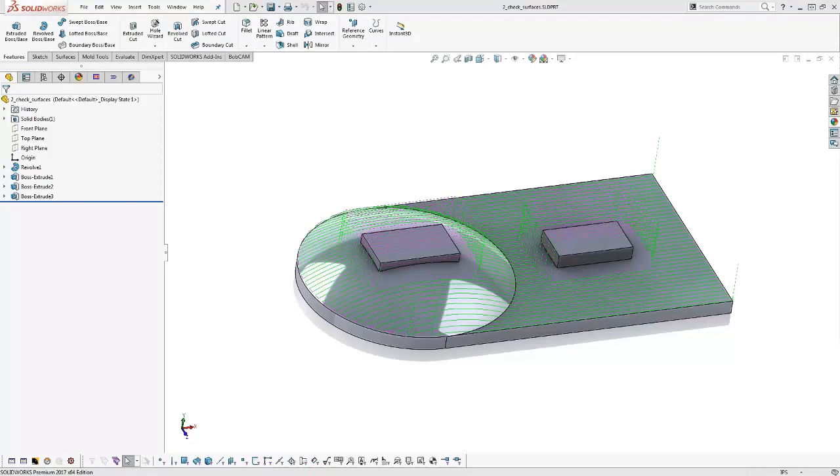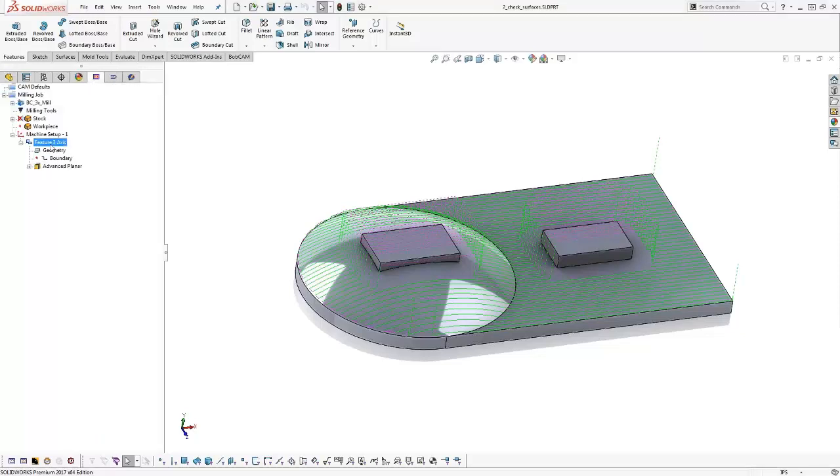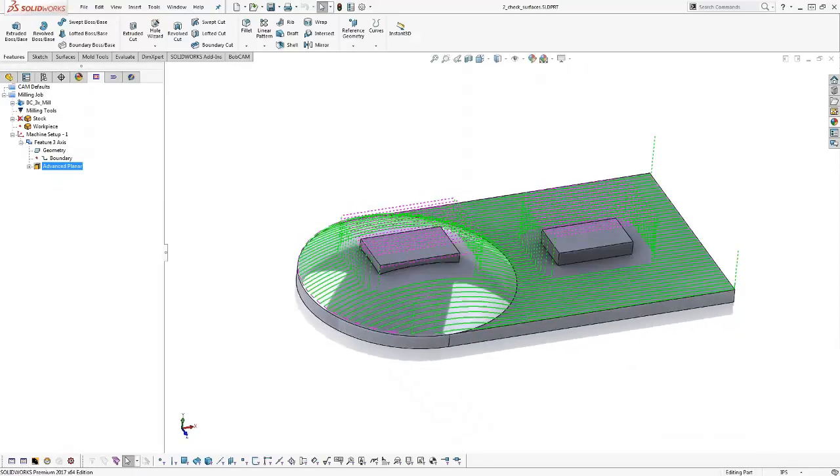And let's look at our next file here, okay? So again, we're talking about CheckSurfaces, gouge checking with CheckSurfaces. And I know it's kind of confusing because it's like, gouge checking, does that mean the toolpath normally gouges? This is more of a surface-based strategy where you're driving toolpath along a surface and then you want to check against other surfaces. So the fact that I'm selecting the entire body may be a little confusing, but again, this is a very, very powerful feature. And we're going to just review this again, okay?